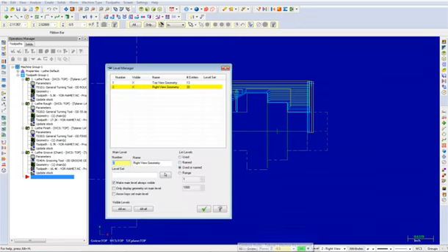When the Level Manager opens, click on 2 in the number column to make it the main level as shown. Now select the All Off button to make Level 1 invisible and Level 2 the only visible level. Select the OK button to exit the Level Manager.